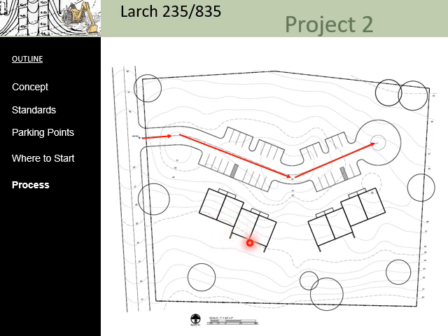Once you've made that drop, now you need to look at the existing contours and see if your idea works. So if this contour, for example, can stay where it is, that's lovely. If it has to come up a little bit, that's fine. If it has to move down a little bit, that's fine. If it has to move down all the way through this tree, that's a problem. And you're going to find some problems. That's part of the process you're going to go through.